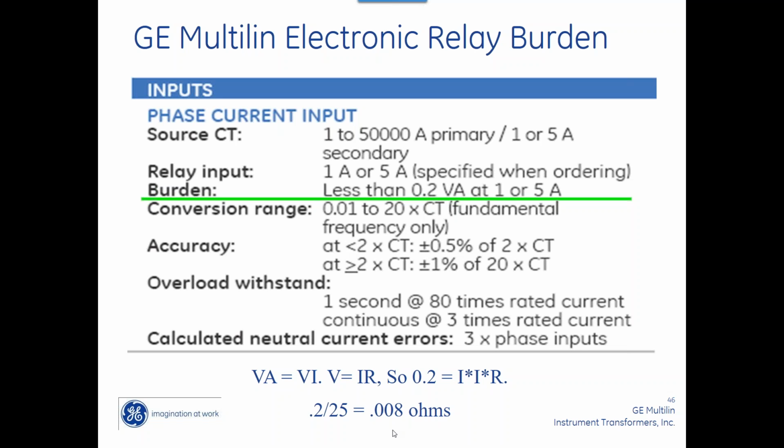With electromechanical relays, it was a real factor. And a lot of the utilities specify like C800. The reality is with the new protective relays, you could go much lower and use a C400 or maybe a C200, depending on how much my lead wire length is, and still be fine.